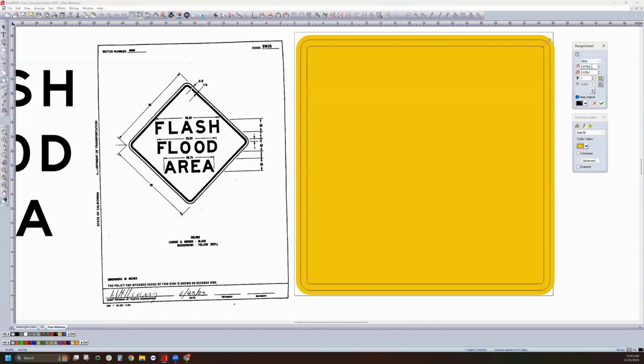Moving down, you have the width of the line, which would be the width of this black part. Right now, it's just a wireframe example of what it's going to look like. Once we apply it, it'll become solid black. In our drawing, it calls for a 7/8 width border. So we have the 0.875 width. Our offset distance is the distance you want that inline or outline, if you're doing it that way, from the edge of your original rectangle or your original object. So in this case, our drawing calls for 5/8. So we have 0.625 in there.